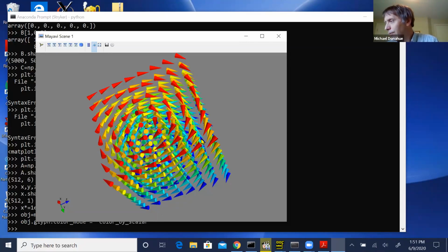Okay, AVF to ODT, can we take the average along any arbitrary direction for a 3D sample? Again, no, it only supports along coordinate axes. If you want to do something like that, you would have to write your own code, involving some interpolation. Although you can use AVF to OVF to maybe help you with interpolation, I'm not sure. But at any rate, the file format for the OVF files is very simple. It's fully described in the documentation. So if you need to work with the raw data to do your own programming, use that as a reference.